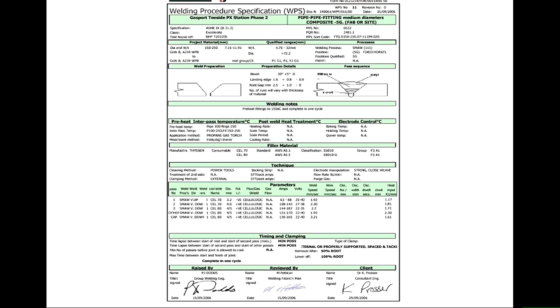So you have absolutely got to control every step of the welding process to ensure that you produce a reliable process in the field. Now this is done before you even start the project. Your job though, if you're a welding engineer, is to make sure that on the project it's actually kept to that standard. And that's much more easy nowadays in the days of digital power supplies, because you can hardwire that into the process. In the past, welders would say, I can do almost anything, and it's my skill as a welder which determines whether or not we get a good joint. Nowadays, we have to work to a certain standard for doing that.